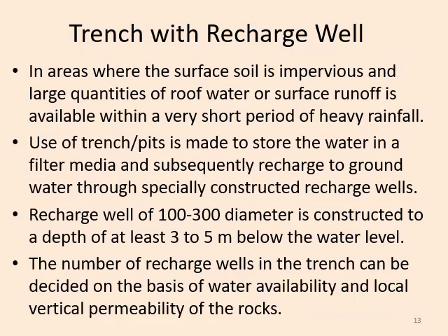Next, trench with recharge well, in areas where the surface soil is impervious. So here soil is a factor. The soil is impervious in nature, and large quantities of roof water or surface runoff water are available within a very short period of heavy rainfall. What is the characteristic of the rainfall? The rainfall intensity is heavy within a short period of time, and the soil is impervious.